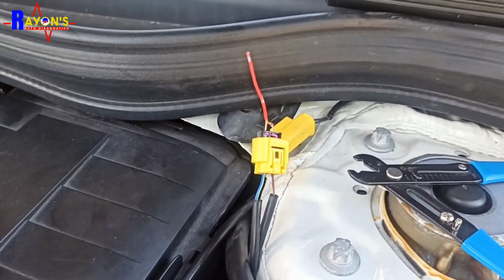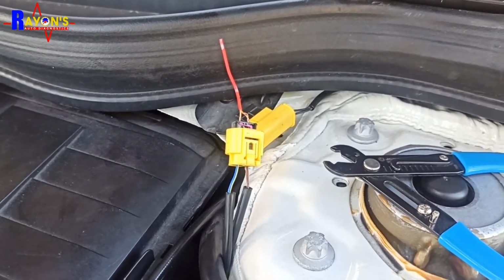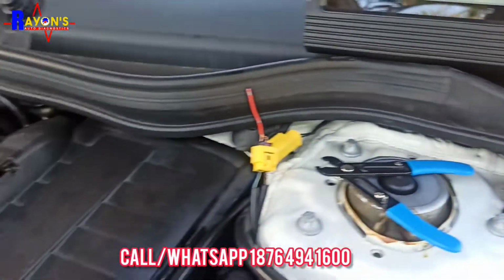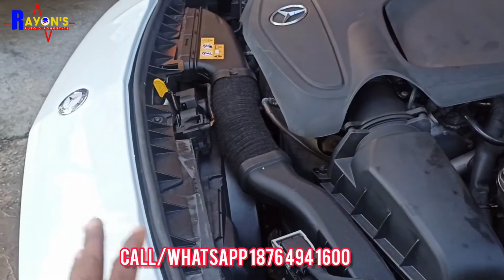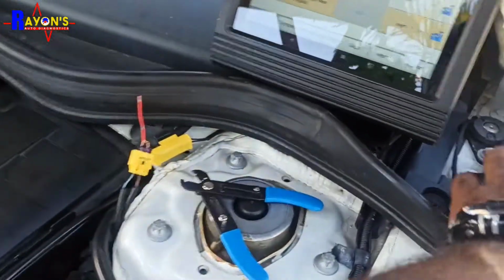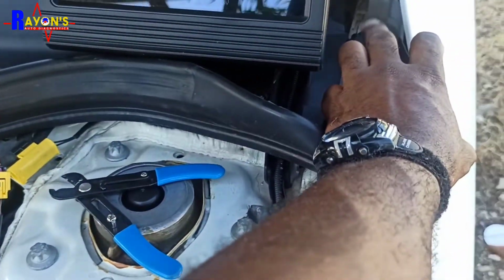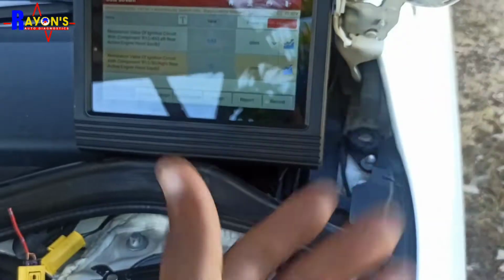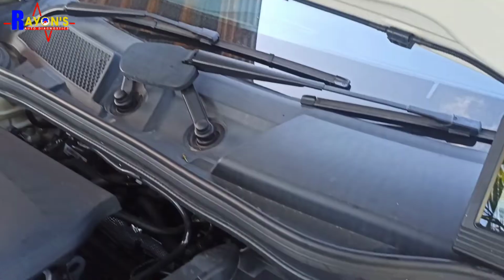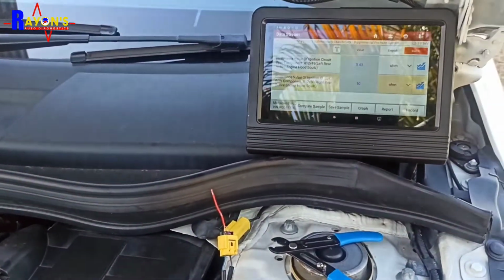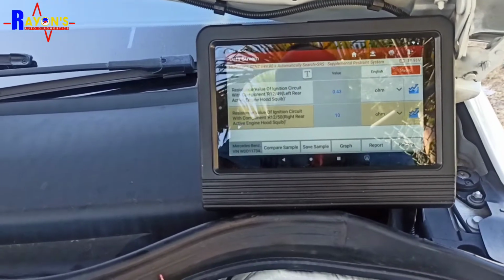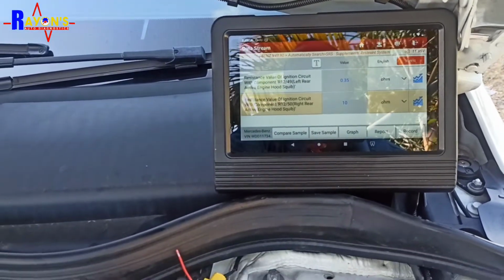And no, this test cannot deploy the airbag module. This is the pedestrian protection system, wherein if something or a person should impact the front of the car, then these two squibs would just pop up the back of the bonnet to dampen the impact of the person coming onto the bonnet. So this won't deploy any airbags. This test is 100% safe to do.